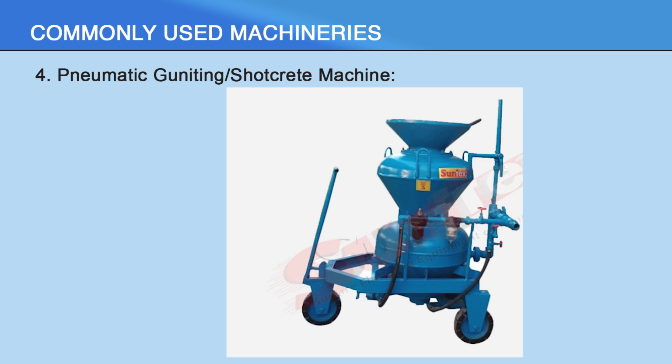For repair work of concrete structures of all kinds, including reinforced concrete and stone floors damaged by fire, weathering, or chemical attack. For repair of cracked walls, piles, or beams of concrete or reinforced concrete structures and masonry. For production of thin walled structures like walls, dams, shells in conjunction with steel fiber or mesh wire. For production of watertight plaster for vessels, tunnels, dams, etc.